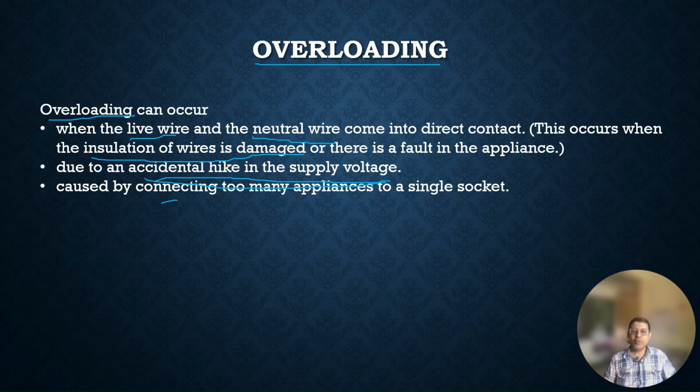Or sometimes you may connect too many appliances on a single socket. Sometimes we have an extension board with multiple sockets, and that extension board has a particular rated current. But now you connect all sorts of devices. It had happened in my own home, unknowingly. As kids, you try to connect multiple devices without knowing the current requirement of the other devices. So that means the extension board will get overloaded. It will spoil the devices which are actually connected to it.